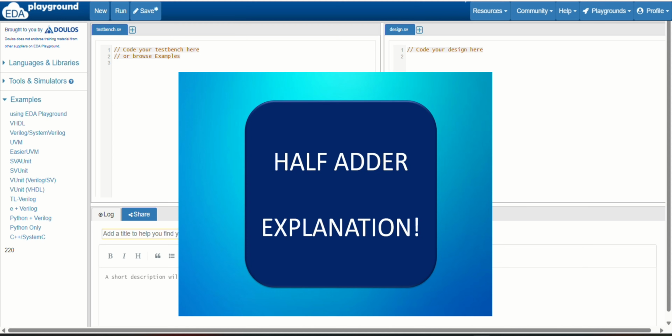And what are those outputs? Sum and carry. If the input is 0 0, then in the AND gate or in the basic gates, what are we getting? A single result. 0 0 output is 0, 0 1 output is 0, 1 1 output is 1. I am telling this for the basic two-input AND gate. Now for this half adder, we have two outputs, sum and carry. For the two inputs 0 0, the output will be displayed on the screen not only once, but twice: one output for the sum and another output for the carry.